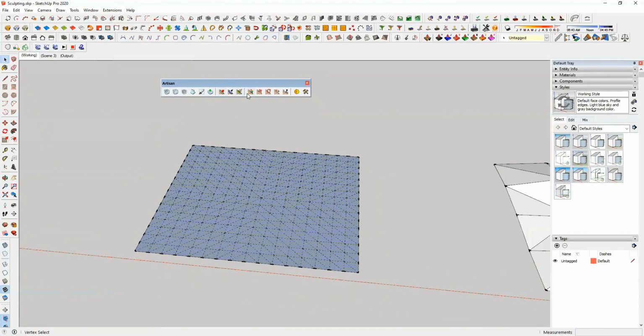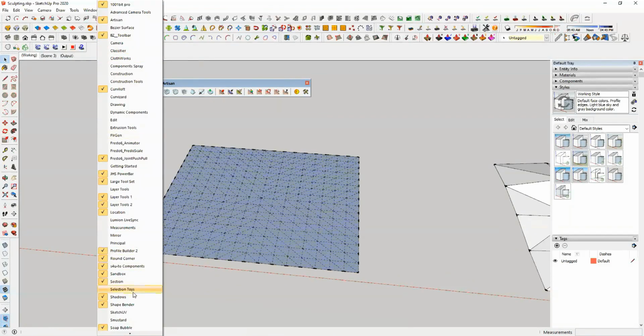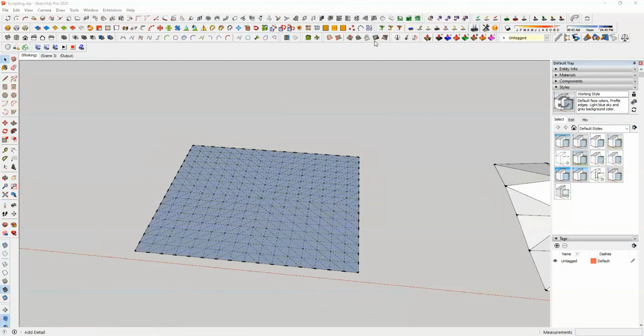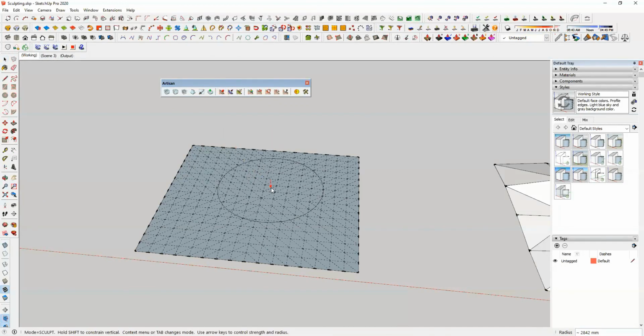Out of the sandbox tool, we had seen that there is a sculpting option over there also. Let's turn on the sculpting, the smooth tool in this one, which is this one. Yeah, the smooth tool will help us in sculpting. We have a similar tool here, but it is a little bit more advanced, and we have multiple options to add more details and less details as well, which is the sculpt tool or the brush sculpt tool.